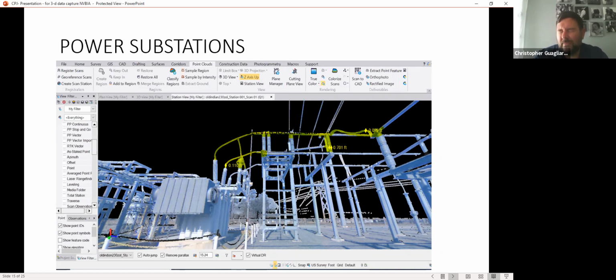Excuse me, 7/10. Sorry. They need 3 millimeter accuracy on all this. That's their tolerance. So you cannot use a survey gun that's going to give you basically half a hundredth or whatever. You need tight stuff in there. So knowing the difference for this, okay.